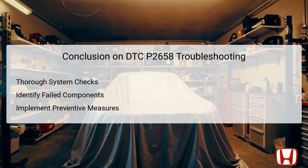In conclusion, troubleshooting DTC P2658 for the Honda Pilot from model years 2016 to 2022 requires a methodical approach that encompasses comprehensive diagnostics, focusing on both electronic and mechanical components. Starting with verifying the DTC using the HDS and addressing any underlying issues with the rocker arm oil control solenoid or wiring is crucial. Identifying failed components accurately not only resolves immediate performance issues, but also informs future preventive maintenance needs.